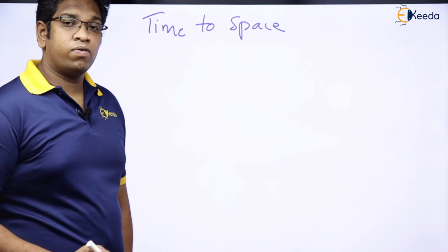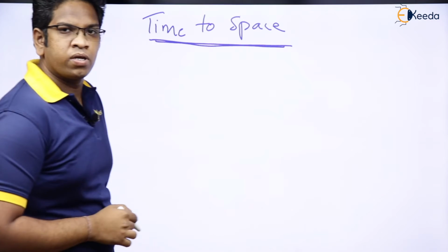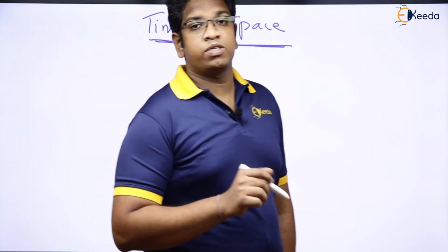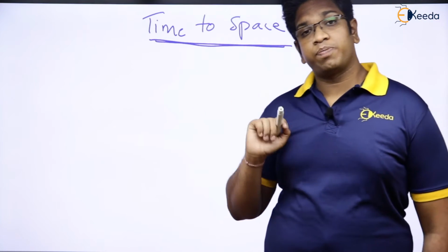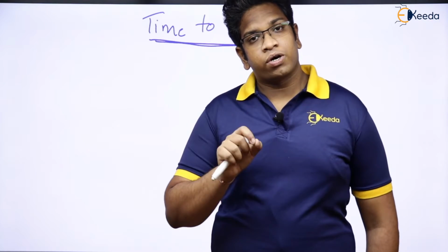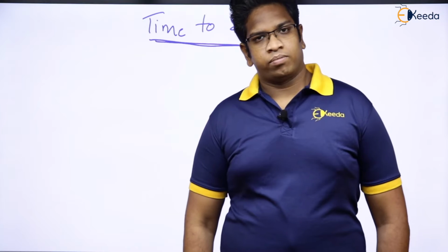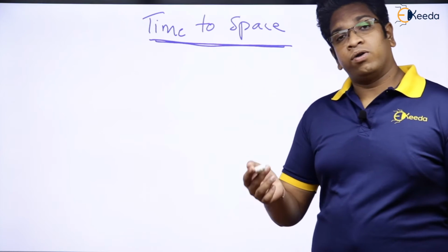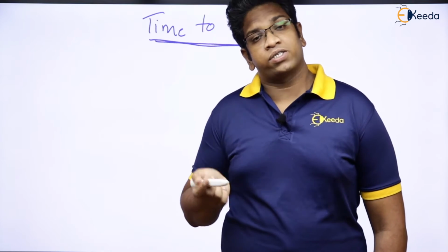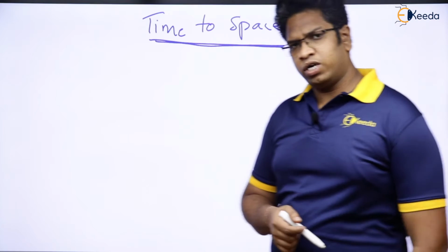What does that mean? What was the conclusion at the end? The conclusion was, if I flow 120 degrees time displaced currents through 120 degrees space displaced winding, I will get one rotating magnetic field which will be of constant magnitude and it will rotate around. It will rotate with the angle of time, and it will align itself with the axis of MMF in which maximum current flows. Already we know that, right? Basics, already we have learned.